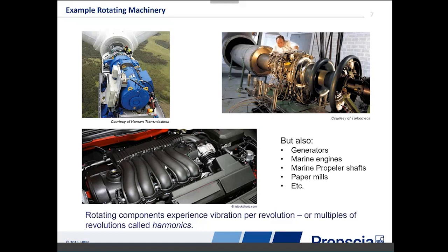So we have to really understand what vibration is directly linked with the main shaft, or a shaft, say, and how is it linked? Is it occurring at each rotation or at so many multiples of rotation, which we call harmonics?